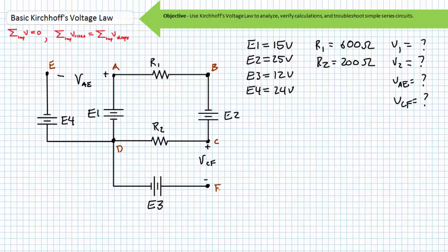What we really got here is several independent loops, only one of which actually includes a complete circuit. My advice is to go after one loop at a time. The first and most obvious loop is that formed by E1, R1, E2, and R2. This is the only complete circuit in this monstrosity, and the only path through which current will flow.